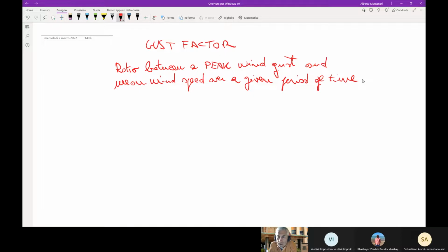So when you have only measurements of mean wind speed, maybe over a 30-second time span, the Gust factor allows us to assess the peak wind speed. When you get wind data, in the metadata, so in the description of the behaviors of the data, you will be given the time scale, which is the period over which the wind is measured. Very precise instruments can measure over a period of about 2 seconds. Older instruments gave the estimate of the wind speed over a minute or over a full hour.